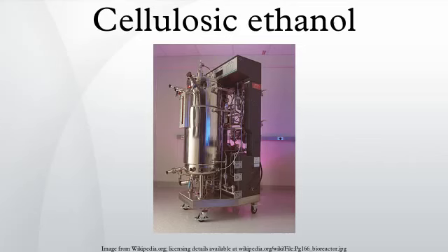Cellulolysis. The stages to produce ethanol using a biological approach are: a pre-treatment phase, to make the lignocellulosic material such as wood or straw amenable to hydrolysis; cellulose hydrolysis, to break down the molecules into sugars; separation of the sugar solution from the residual materials, notably lignin; microbial fermentation of the sugar solution; distillation to produce roughly 95% pure alcohol; and dehydration by molecular sieves to bring the ethanol concentration to over 99.5%.